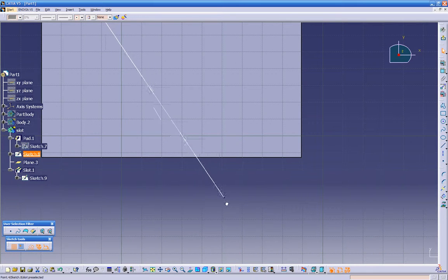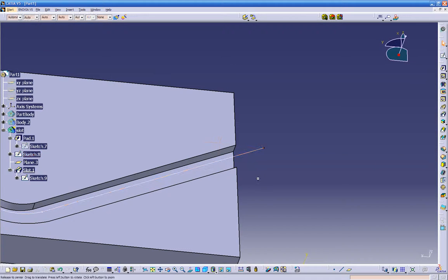But if you don't want to move it this way, let's do Control Z. If you want to go same direction, there's a couple of ways of doing this. You can create a line, and then make sure this is in the construction. And we can go to the trim option. So you can grab this line, and we can trim it with this line. That's one way. Control Z to put it back, or we just click on this right here and same thing. Okay, so now if we get out of the sketch mode, our model is automatically updated.